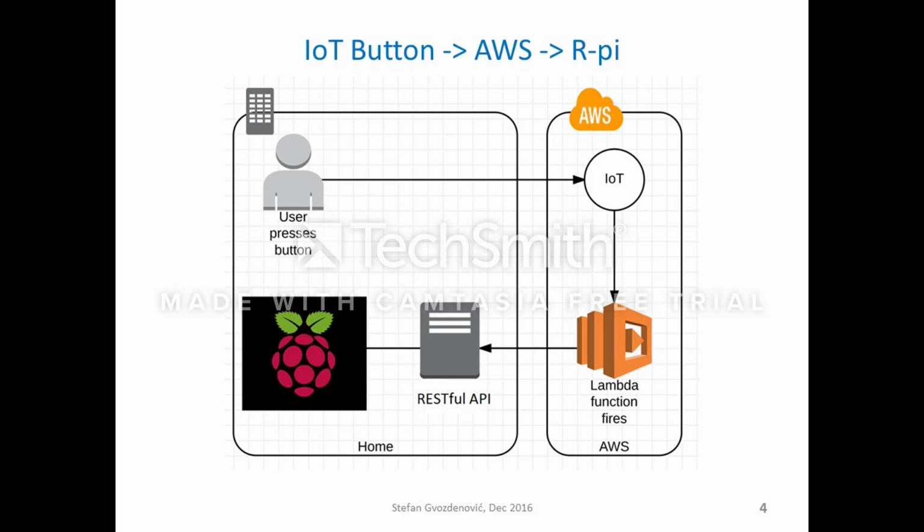The website hosted on the Raspberry Pi then sends serial commands to the radio, which actually transmits several commands to make sure switching is reliable. This redundancy is because the light bulb does not acknowledge received packets, so we have to send several commands to make sure the switching is reliable.